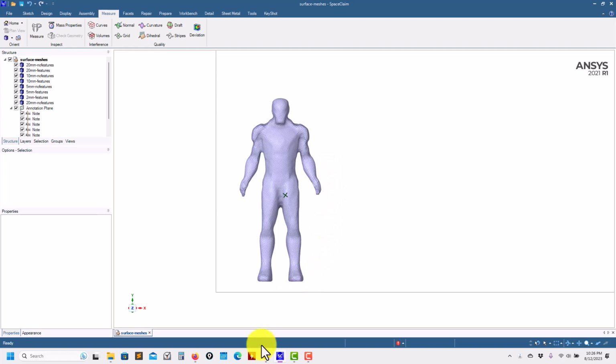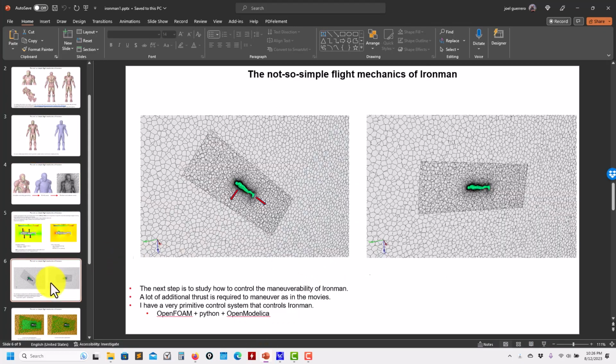So to do the polar study, I think the best way will be to create a round domain, so you can rotate it. It's easier. Instead, if I give you a rectangular one, you need to redo that mesh. And I don't want to work for the moment with overset meshes.